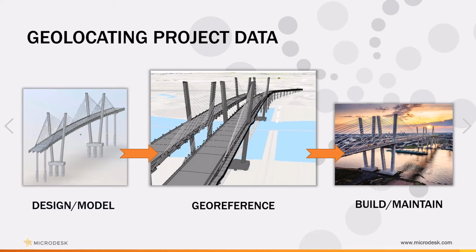In the first screen recording that we have here, we'll see how this process is done from the perspective of Civil 3D. We start in this recording from a site plan that has a correctly positioned survey point. And we use the Map CS Assign tool to assign a coordinate system. This can be searched by name or well-known ID. And we assign that intended coordinate system. And then a map can be added to that project to verify that that element has been properly positioned.